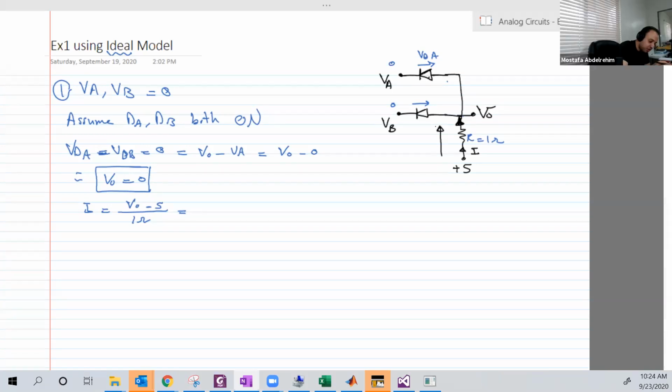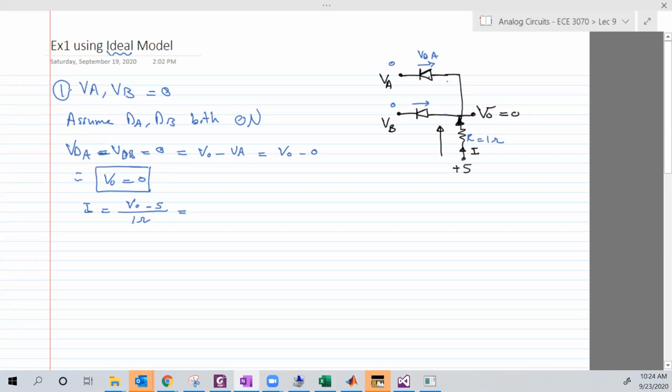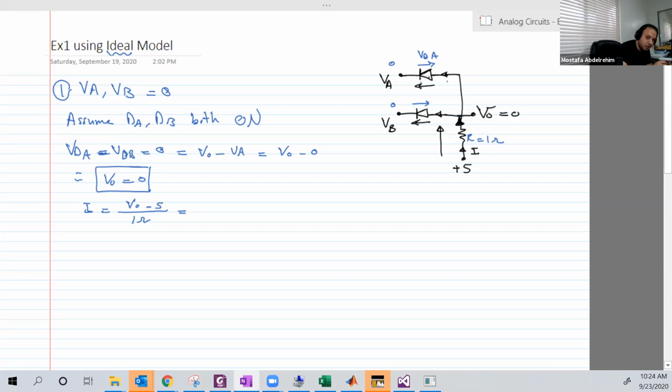Of course, because basically this node is 0 and this is the higher voltage, then the current should be going in that way. Then it will be branched to IB or VDB or DB and DA. And we know also that when this diode conducts, or is on, the current should be flowing in that way. The same, of course, for that diode as well. So if this is moving in that way and this is also moving in that way, the source itself should be moving in that way, entering the node, then branching.